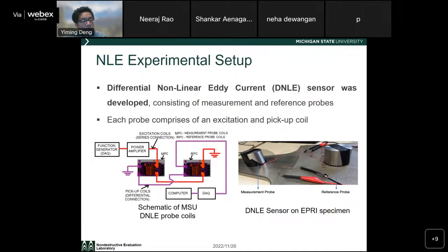So the idea of differential measurement is, different methods are going to have different ways of defining how you do that differentially. But the basic principle is you are doing some kind of subtraction in your data acquisition. So instead of doing that in the post-processing of the signal, at the sensing stage you are doing some subtraction there. It's either subtraction from the signal from the same location, where you have the differential configuration of a sensor there.